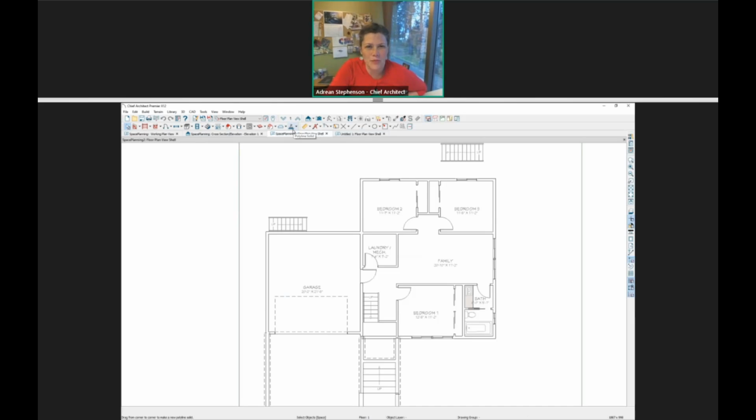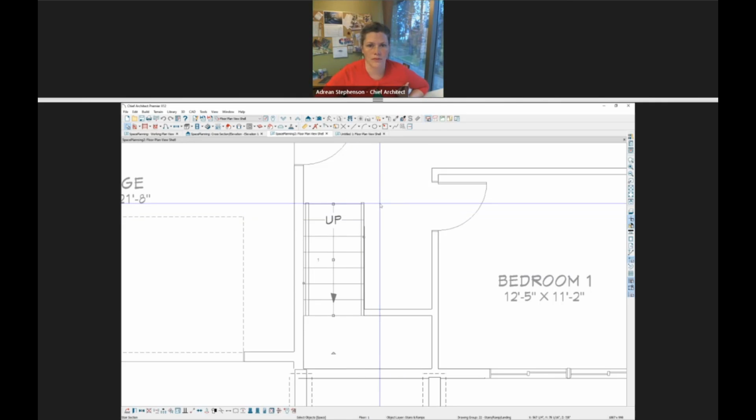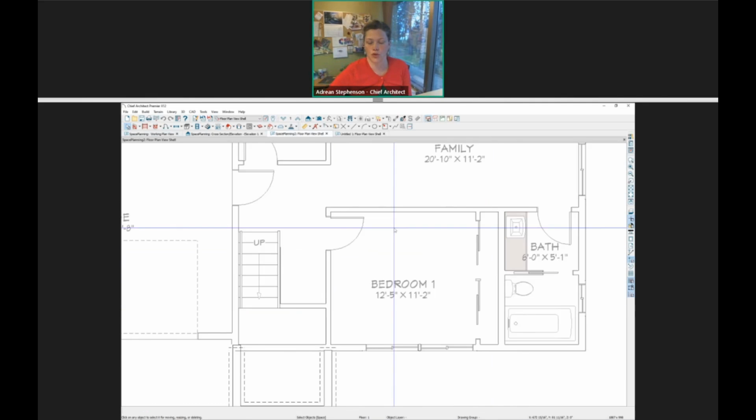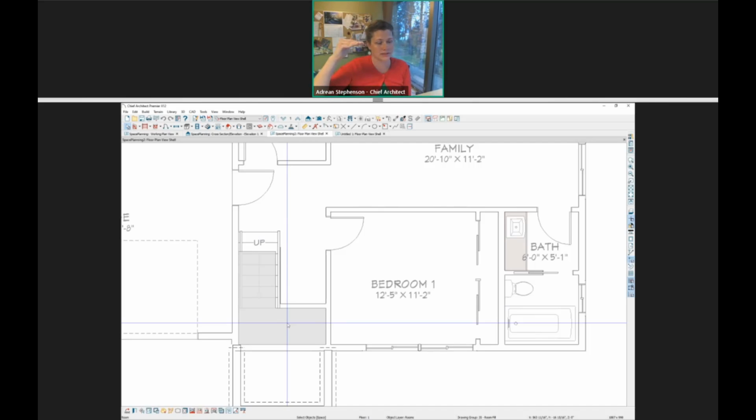Maybe we can look at some ways that stairs actually work to snap together and to hit a landing. This is the plan that I did the two stairs on. It's essentially a U-shaped stair with a landing in between the two floors. Yeah, that's the kind of situation I have with a split level. So when we have the split level room, I'm on my lower floor here, and I have one stair, and it needs to start in the middle of a room definition at the bottom. Then when you drag it, you bring it up so it overlaps whatever the wall is for that next platform height.